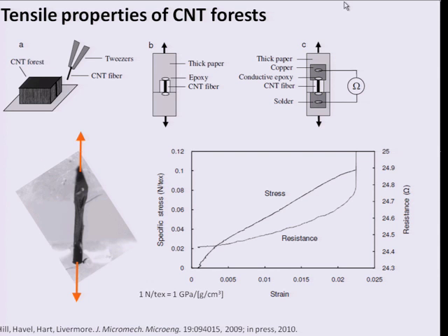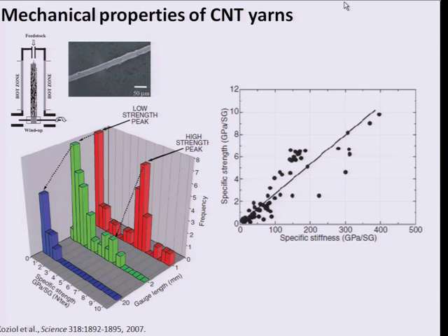The fact that the resistance increases gradually indicates that this kind of long strain behavior of the nanotube assembly is governed by accumulated failure of the individual nanotubes in this strand. And this is very far from the highest strength that's been measured for yarns or cables of nanotubes, but suggests that the load transmission between the tubes and the straightness of the tubes is really important for getting that high strength characteristic. And so far, a lot better results have been achieved by spinning nanotubes directly into yarns.